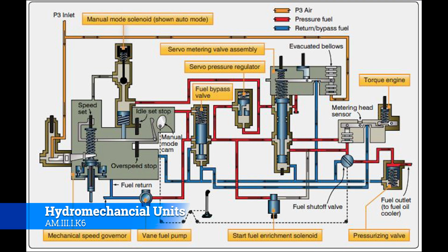Okay, so a hydromechanical unit is still in use today. They're still out there. You'll still see them, but by and large, you're starting to see them go away to these either fully FADEC engines or hydromechanical units that have electronic fuel controls. So let's start with just a regular hydromechanical unit, and then we'll talk about one that has an electronic fuel control.